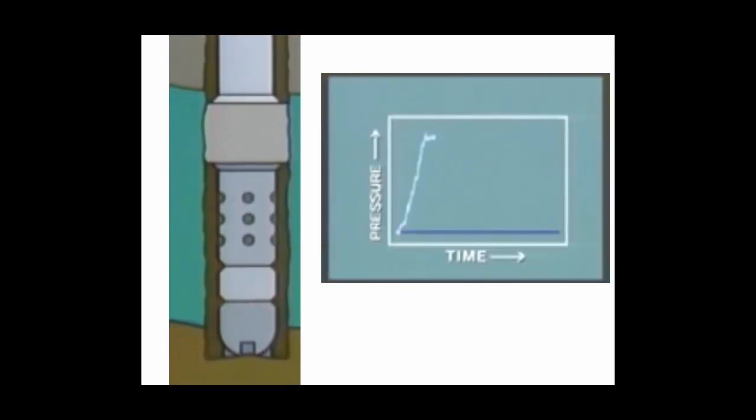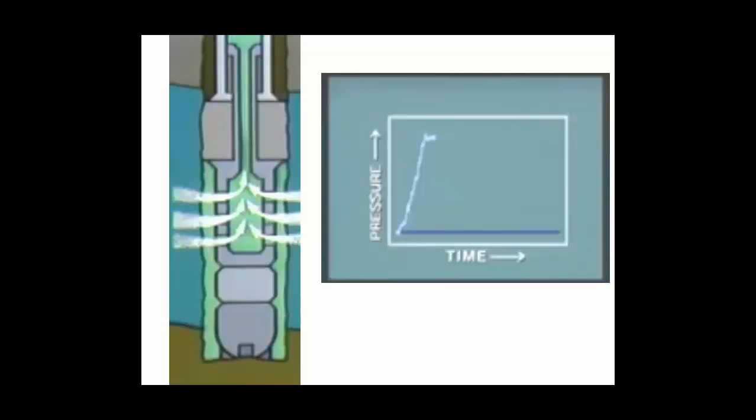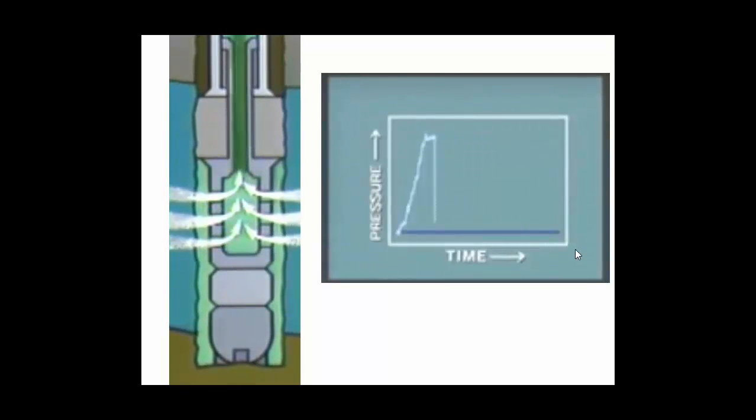Pressure is measured at the very bottom of the tool string and also within the tool string itself. The gauge will now record the pressure imposed by the hydrostatic head and any squeeze pressure developed when setting the packers. A flow valve is then opened and the formation fluids are free to flow into the low pressure drill pipe. As the fluids fill the drill pipe, the pressure increases. This is the initial flow or pre-flow period and is usually of short duration, typically 5 to 10 minutes. Its purpose is to relieve any built-up pressures that may have occurred in setting the packer or packers, or any supercharging of the reservoir due to mud filtrate invasion.